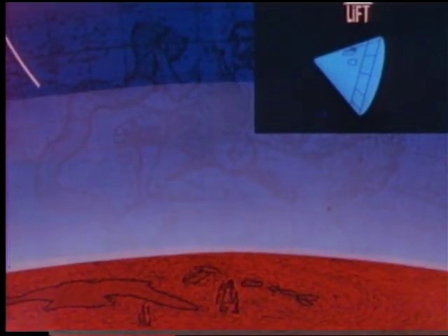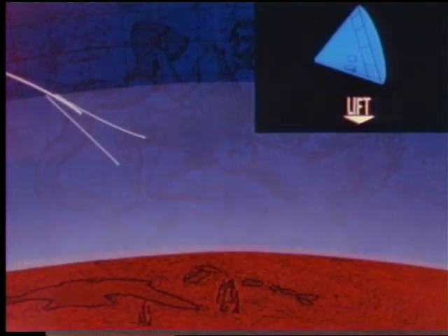If the entry angle is steep, a lift-up attitude can be held to bring the spacecraft onto a safe entry path. If the angle is shallow, lift-down can achieve a safe entry. Therefore, the entry range, or entry corridor, is expanded.